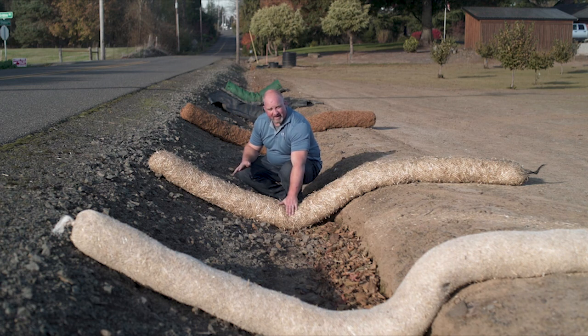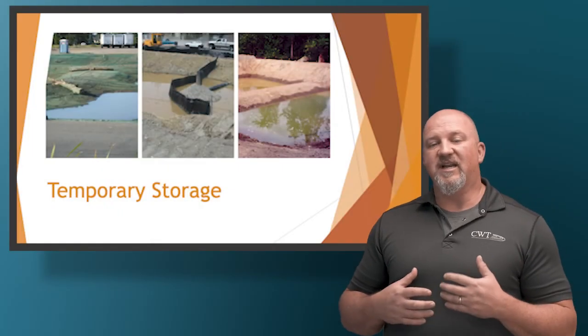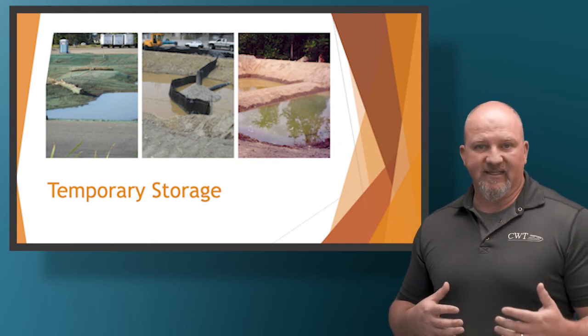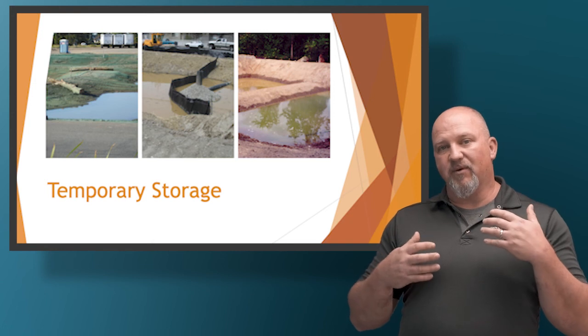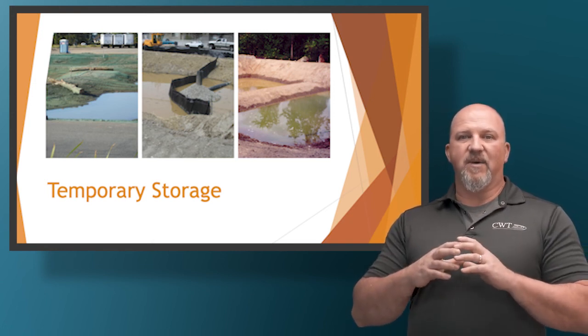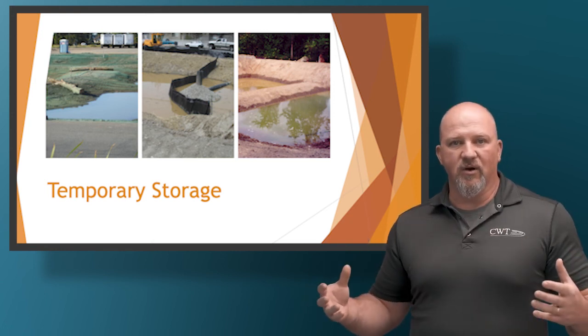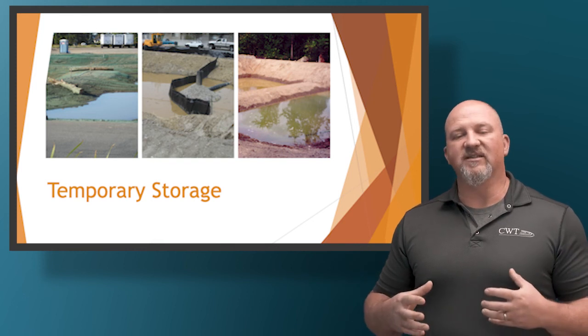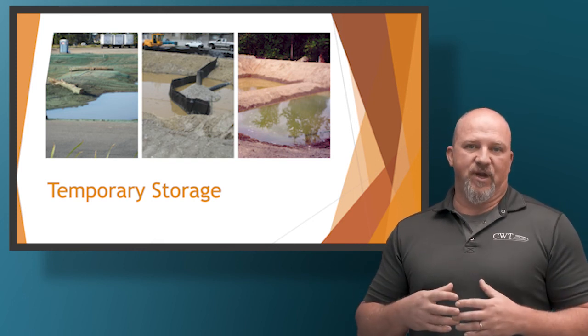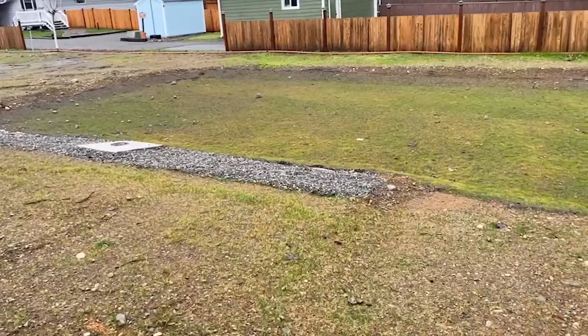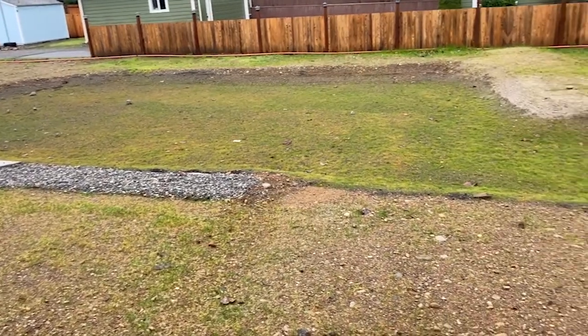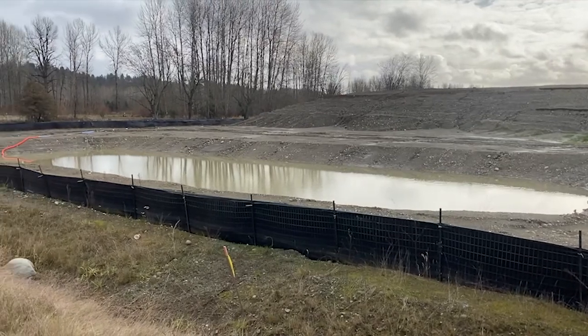and then being checked up by this dam again. The final consideration that you need to have for your conveyance is potentially the need for storage. We're talking about temporary storage here, and we're not talking about necessarily a huge amount of water when we're talking about these smaller projects. But you may need to have a place where you can reside the water for a period of time to allow gravity to take hold of the particles so that you can get clean water in your discharge.